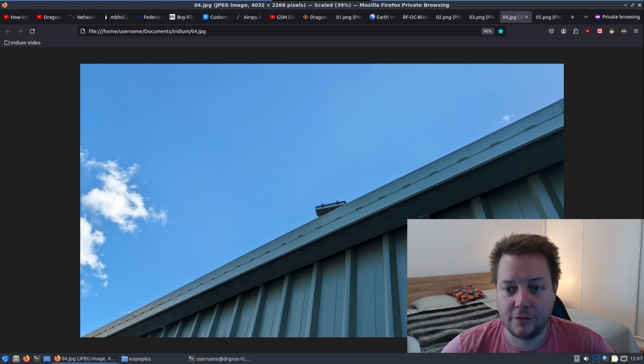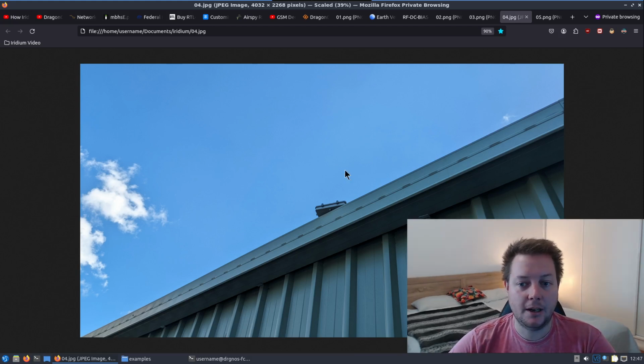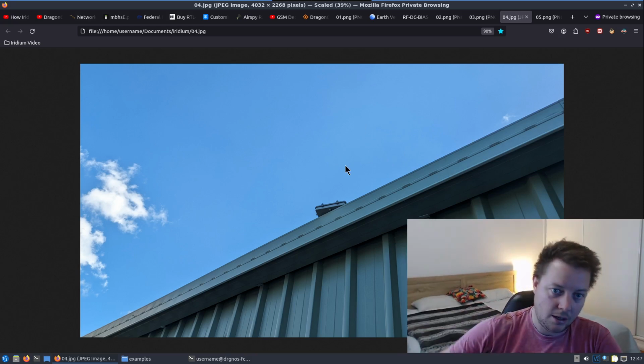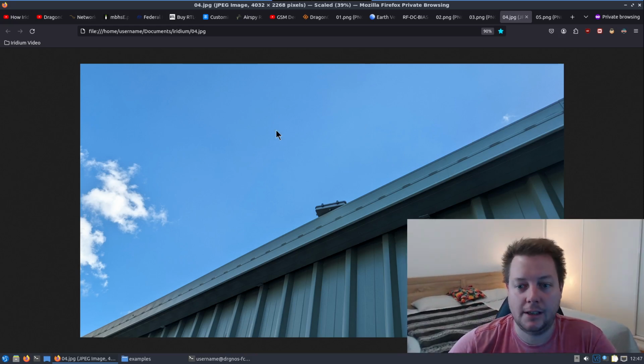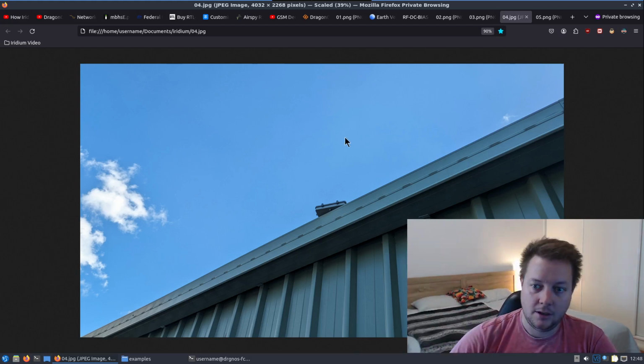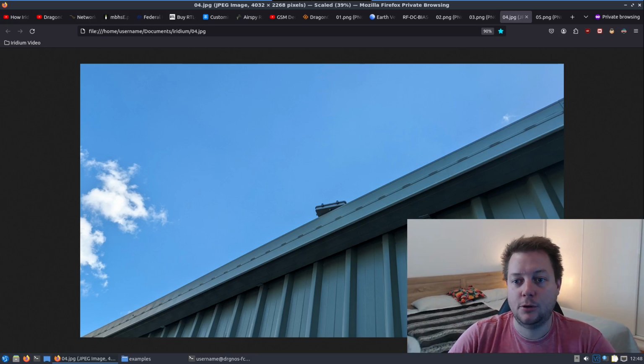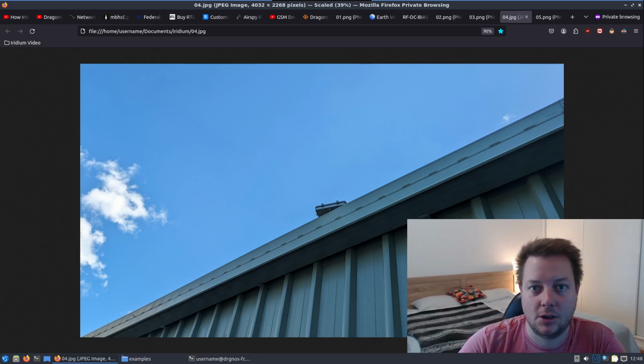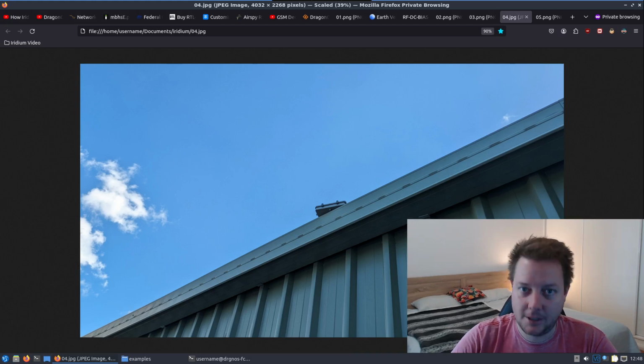And here's an image of my antenna sitting on top of my garden shed. It's quite high off the ground with nothing but blue sky and clouds above it. If you place your antenna very low to the ground, where its view of the sky is obstructed by trees or man-made structures like buildings and houses, don't expect to capture any usable data from Iridium satellites.